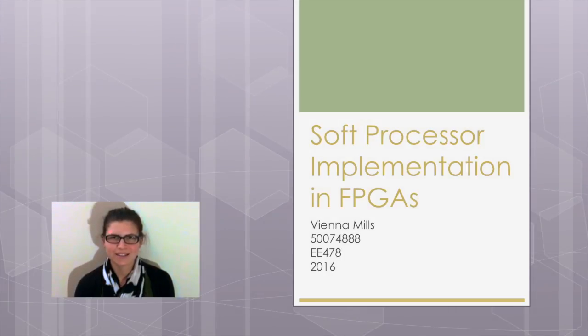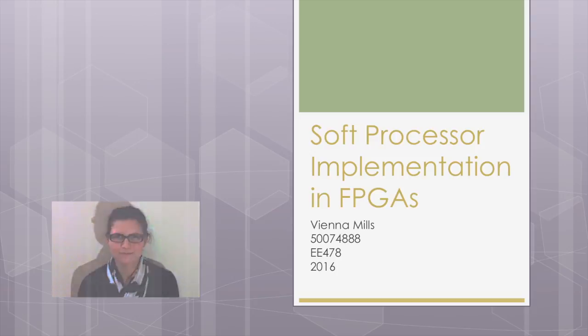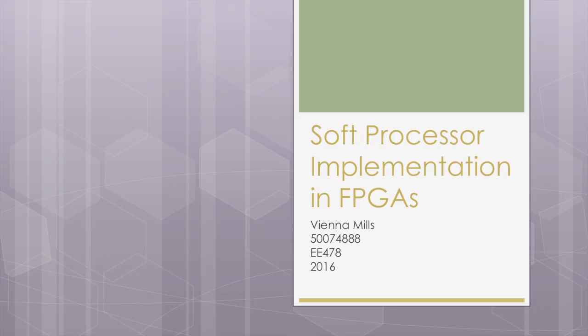Hi, I'm Vienna, and today I'll be talking about soft processors, more specifically how they are implemented in field-programmable gate arrays. Soft processors control IP blocks that are accessed by the processor as peripheral devices or by using custom instructions.